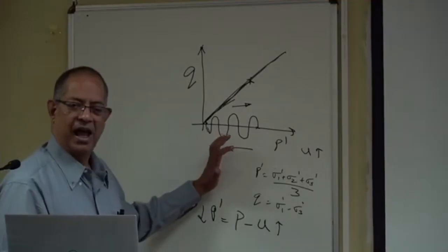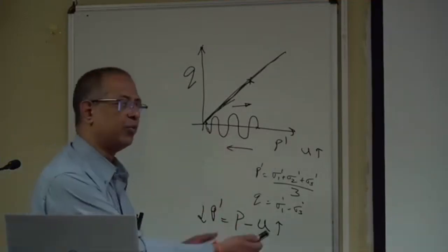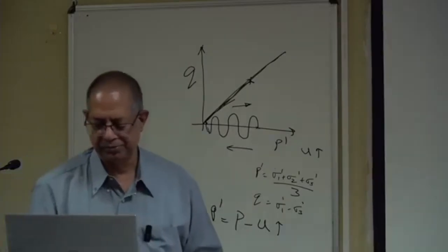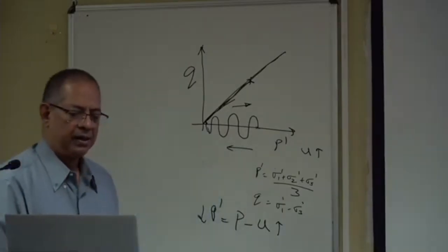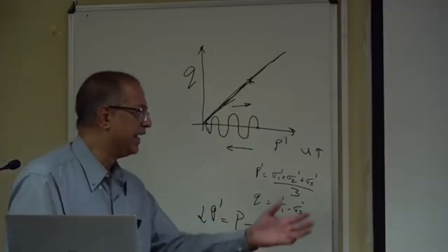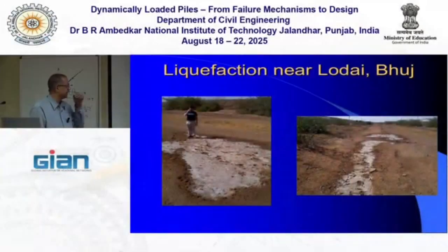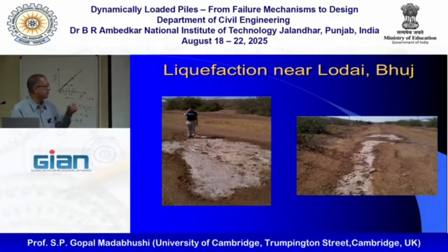There's a framework, and you want to see whether the framework works for the real soil or not. So, of course, at many locations, these are the pictures we have taken. This was my former student and current colleague, Professor Haig. One of the things that happened in the Bhuj earthquake was that because it's all salt marshes, Rann of Kutch, when the sand liquefied, the salt water came to the surface and dried out and left the salt. So we could exactly map how big the sand boils were even 10 days, 20 days after the earthquake.